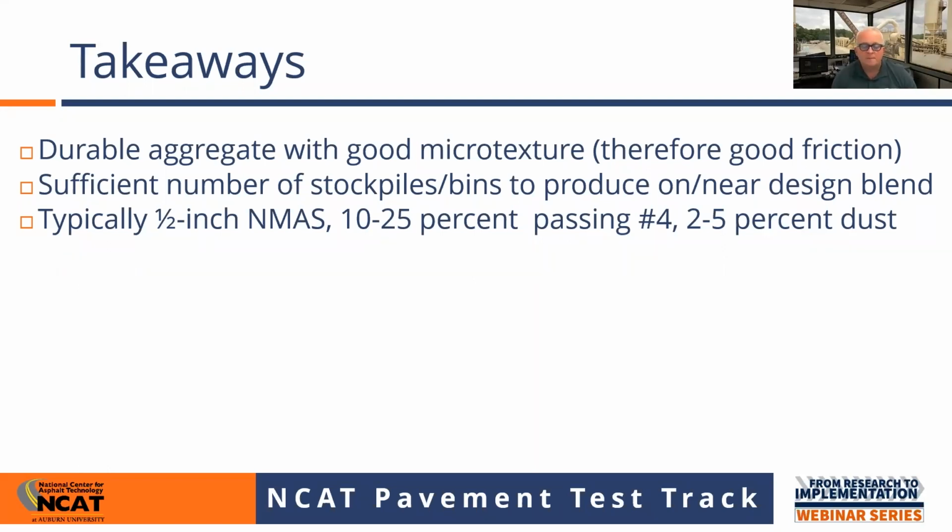Because with these mixes, when you put an OGFC down, design it right and pave it right and have just a super good permeability, over time the permeability goes down because the mix kind of seats a little bit, and then it gets filled up with sand and rubber particles and some other things. So the permeability tends to go down over time.